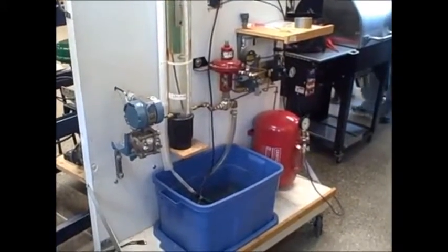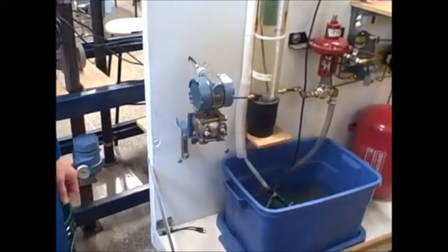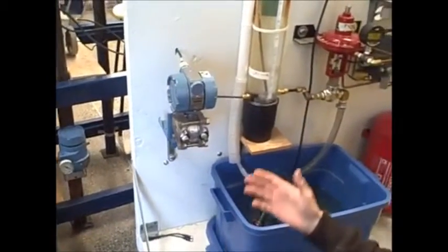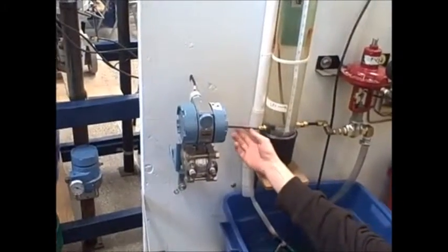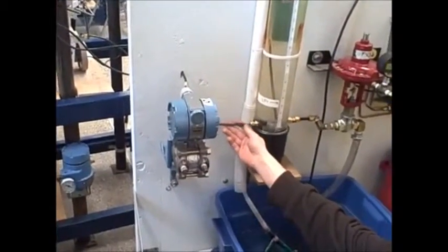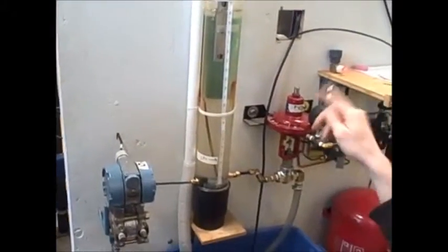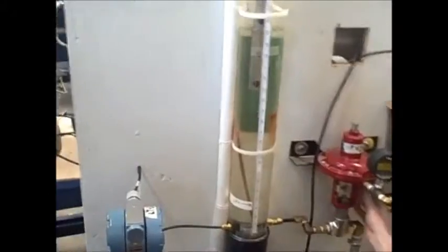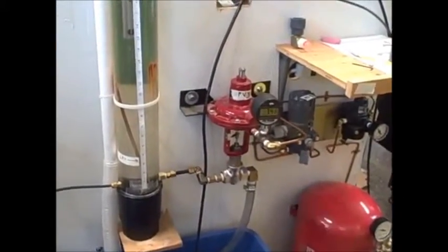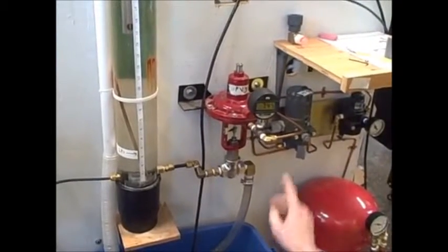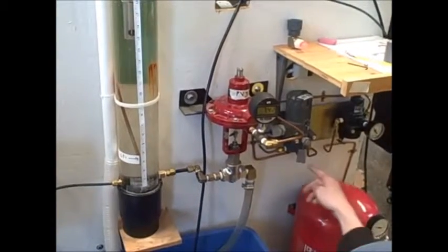Okay, what we have here is a system set up. We use a pressure sensor to indicate a level, so it's our level transmitter, and it sends a signal to the PLC. It senses the pressure from the level of the water and converts that into a signal, and then the PLC does all the thinking. When it comes back, it sends a signal to this pressure transducer to change an electrical current into a pressure, which is supplied from our air supply here.